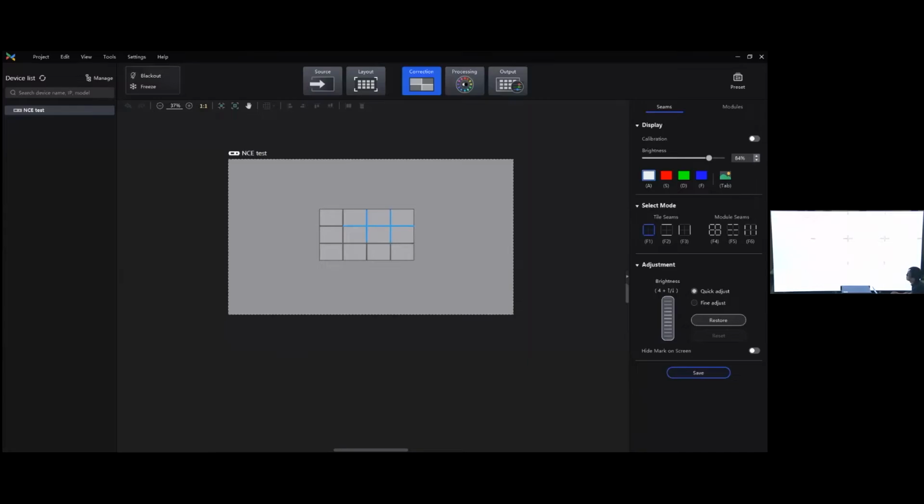Before, in the past, you had to do many calculations. If you found a line you needed to adjust, you had to find which controller was loading this area and which receiving card in this cabinet, and remember the order of the controller and the receiving card. Then find it in NovaLCT. But now the only thing you need to do is put the mouse on the LED display, select it and finish the correction. Quite interesting. Welcome to try this function in VMP.